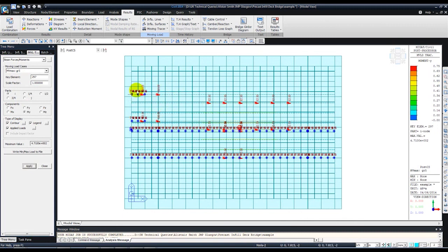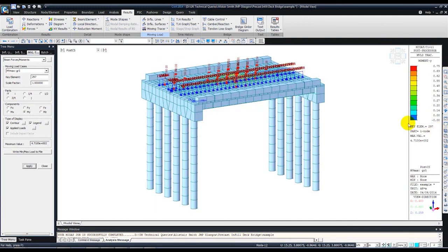That's load model 1 axle, and the load model 3 axles have straddled in the transverse direction between lane A and lane B, and that's how this shows the arrangement of the vehicles causing the worst bending moment at the midspan.